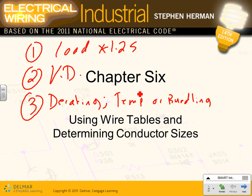When we size a conductor, you have to do three calculations. Calculation number one is based on the load. That's easy, so really there is no difference. You take your load, full load amps, multiply by 1.25, and size your conductor. No gimmick, nothing. Let me tell you one little thing.